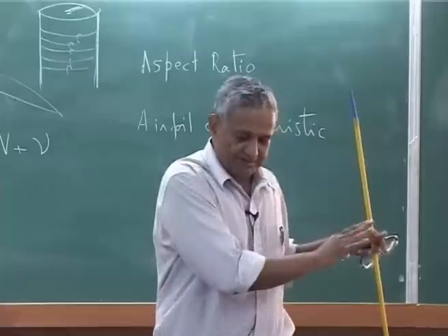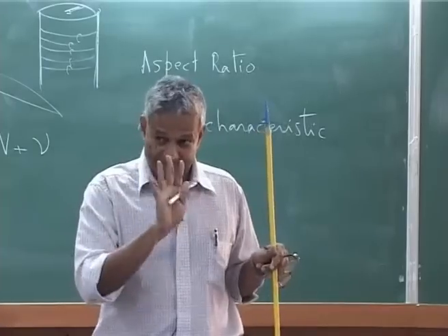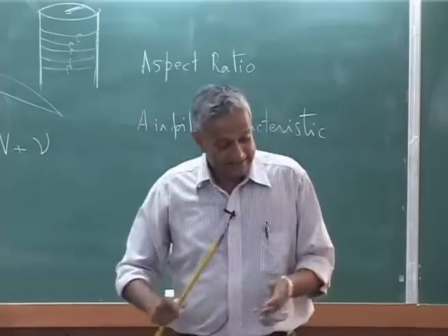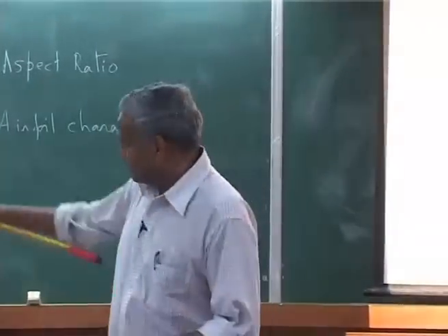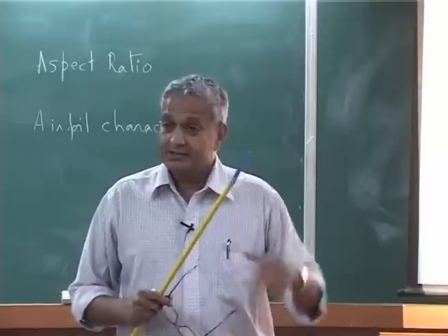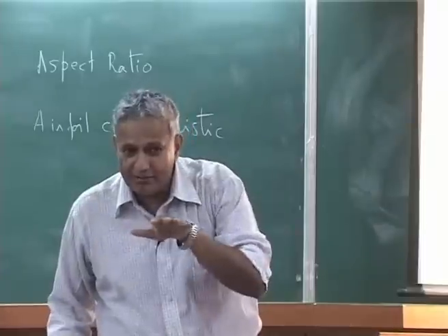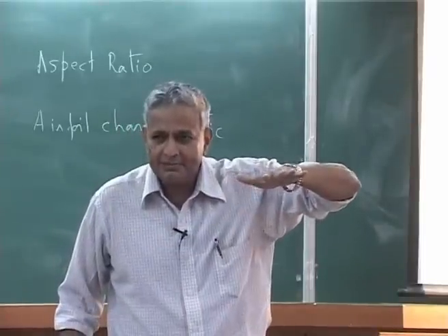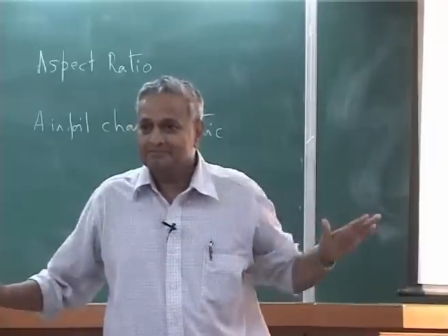There is a theory called dynamic wake theory, which is somewhat similar to this. Please understand that is the model we use, dynamic wake. We do not model this, we use another theory to get the time varying inflow at the rotor disc. Till now we use constant inflow, it does not vary with time, constant and uniform everywhere.